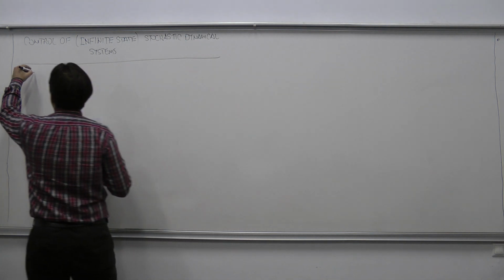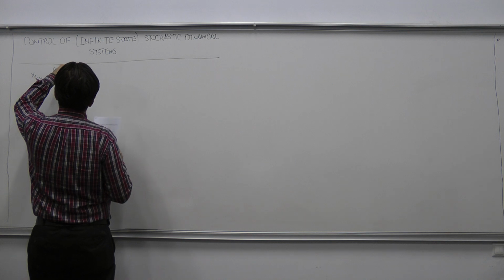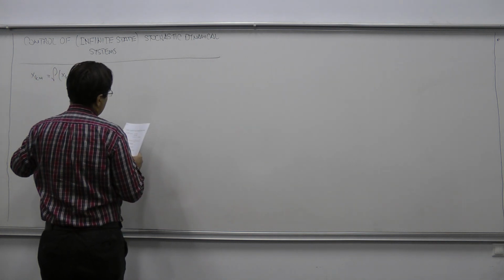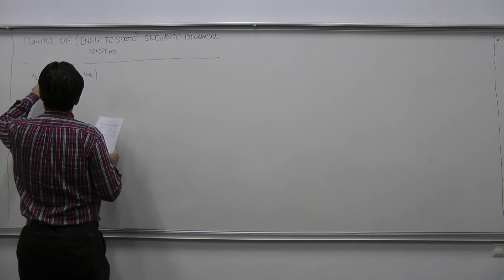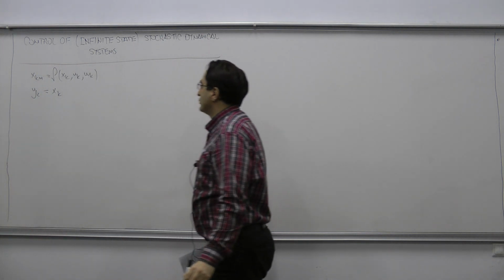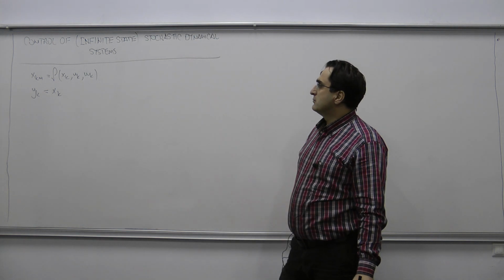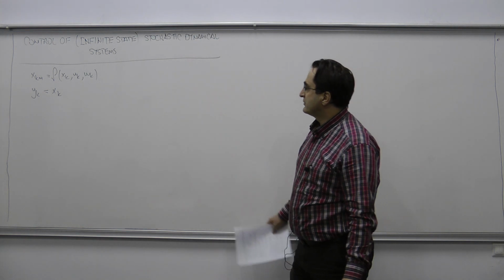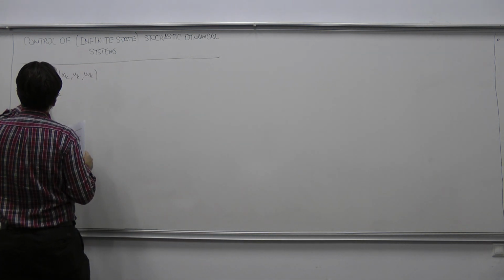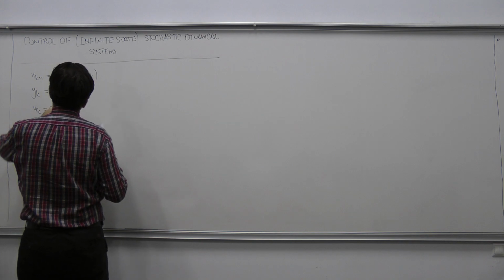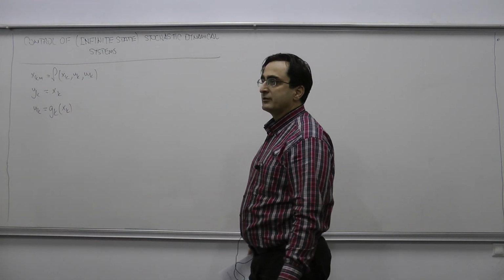So we have the system equation x_{k+1} is equal to f of x_k, u_k, and w_k. And I'm still considering the complete observation case, so we don't consider the partial information case yet. So we exactly measure the state vector, and u_k is going to be given by a feedback policy which is Markov, given like this.